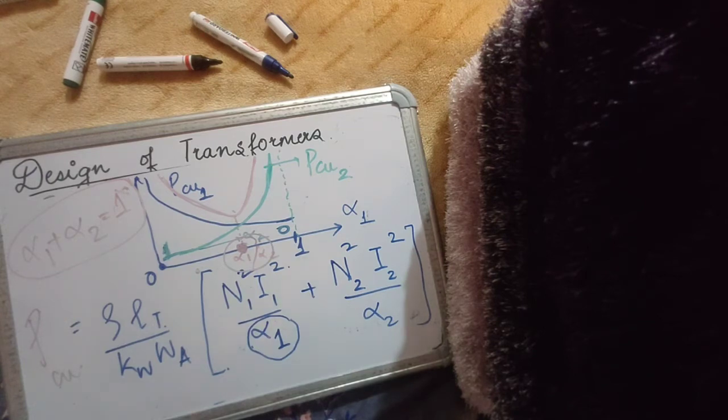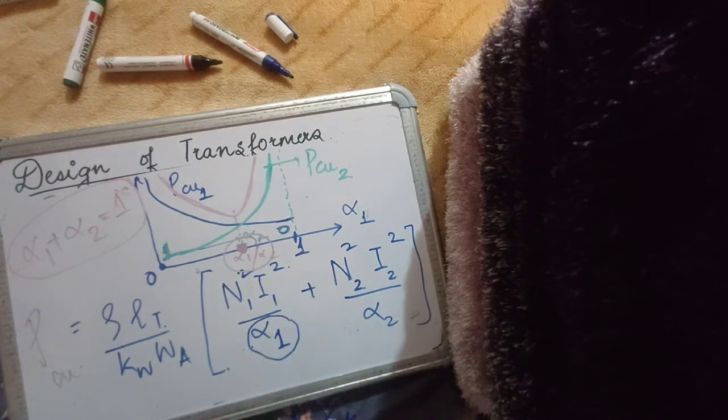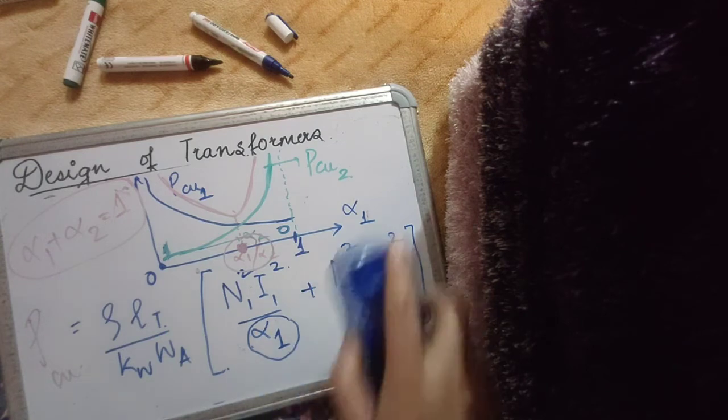When you say it's a high efficiency transformer, why do you say the copper losses are minimum? Because the areas that you have given to each winding, allocated to each winding, the cross section of the conductors that you have chosen, or the cross section of the core that you have chosen, you have made all these choices on the basis of various constraints like copper loss, and sizing and maximum flux density, etc. So that is a good design practice to design transformers, keeping all these constraints in mind. So this was about transformer design.